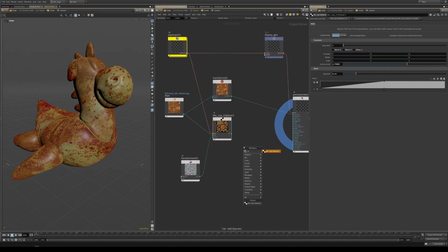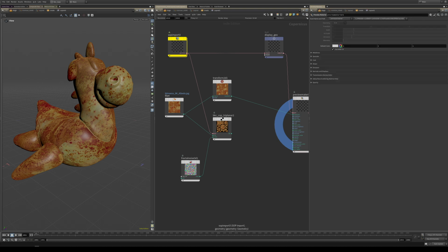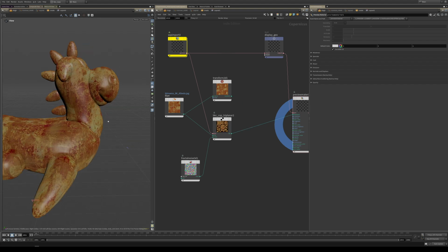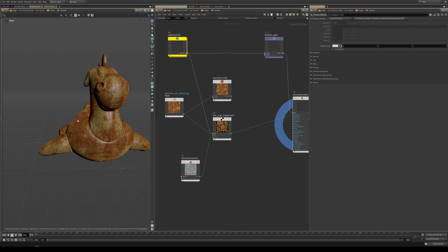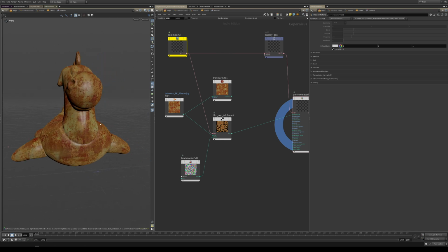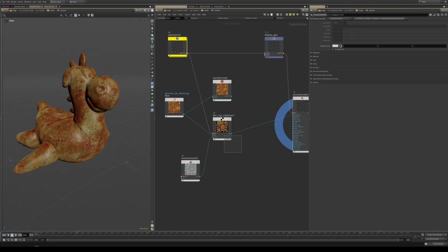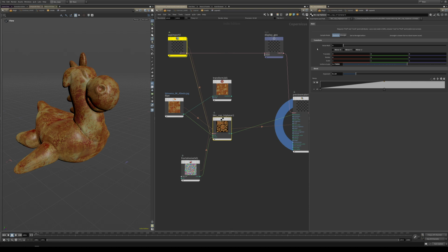So we can simply add our HDA to the scene, which I have one already, plug our geometry in and our texture file in the RGB channel and plug this into the base color. And already you can see we have a better transition between the seam line and other parts, like in front here. And we can change a few settings here.